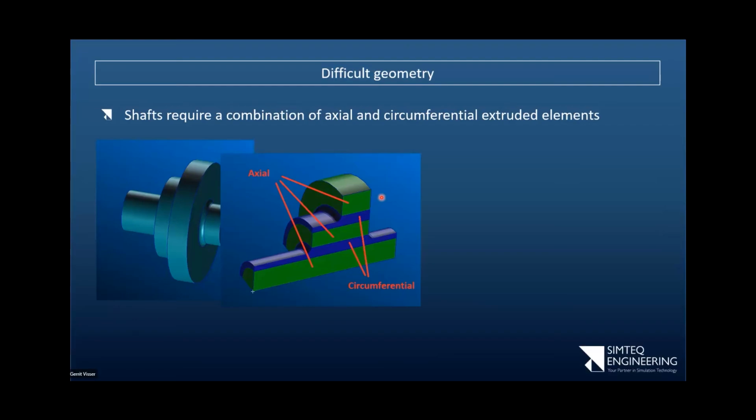extrude it in that direction, and I'm talking as if I'm doing it manually, but it's just explaining how it happens in the background. So your mesher can do it on its own for all I care. Okay, so in that case, it allows me to have different elements on that inner edge as the outer one, a different number there and there. And this, I can have any kind of mesh on that front face.